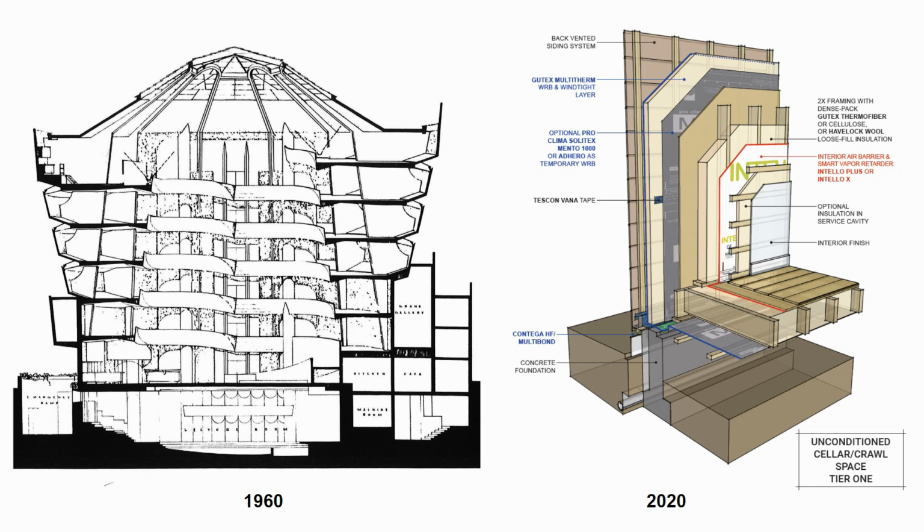And then on the right, you have a state of the art basic house envelope now. This is from a passive house manual, passive house being a high performance building standard. But the point being, it's very complicated now. The passive envelope of the building has become very complicated in recent years, and it's because of several things. One is that we are demanding a lot more control of the interior environment, and that causes us to need more of a separation between the inside and the outside. And then once you do that, you need to understand building science and anticipate how liquid water, water vapor, heat, and relative humidity behave.